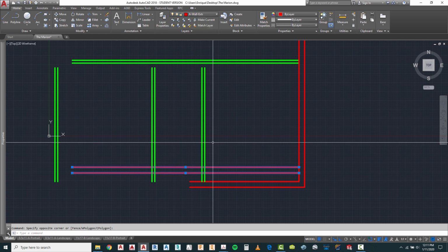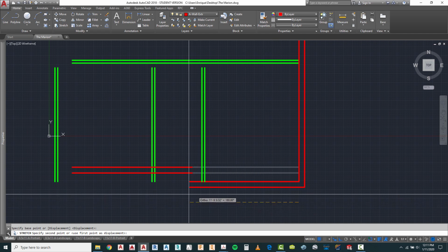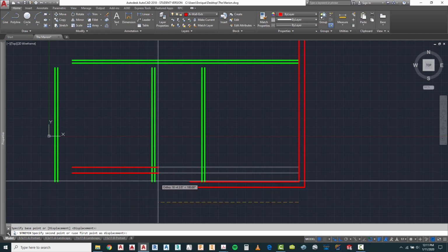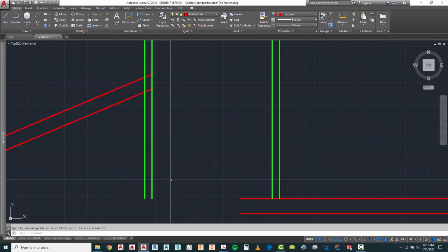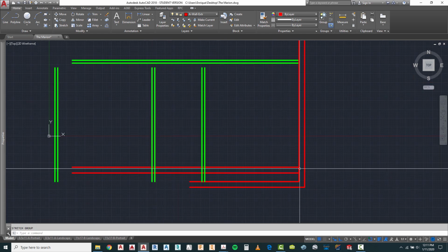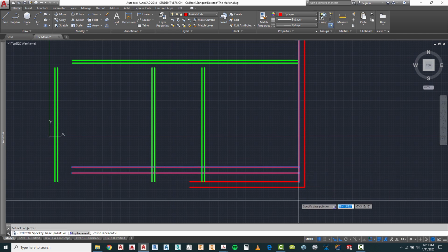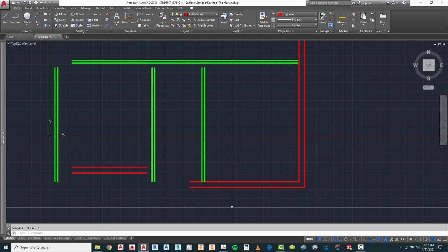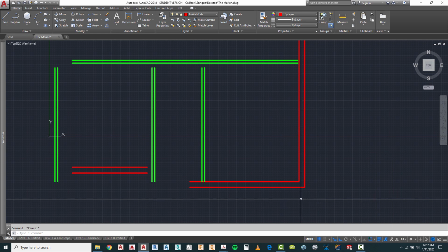to a wall exterior. Using the stretch crossing command, I'm going to get it out of here so it does not confuse. So I'm going to click there, right click, start here, and I'm going to move it to somewhere. In fact, I'm going to move it to this point right here, that intersection. Now let's undo because I didn't do what I wanted to do. I'm going to do the stretch command right in here first, and I'm going to do it to here. I'm going to make sure that my perpendicular was set in here, which it was.